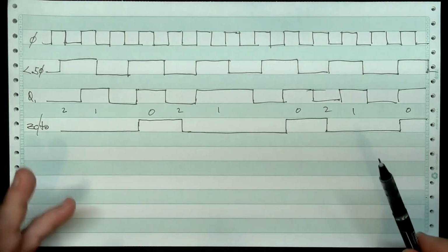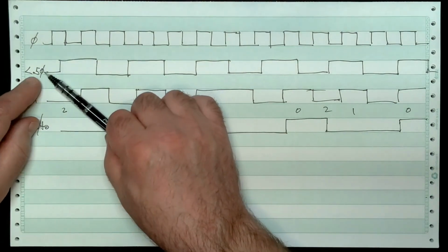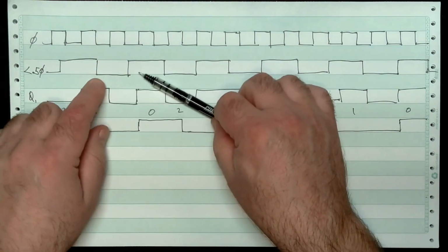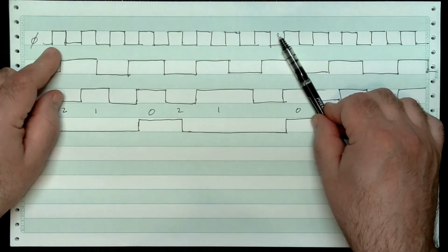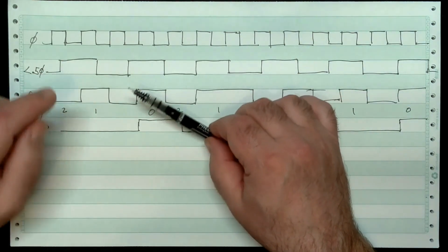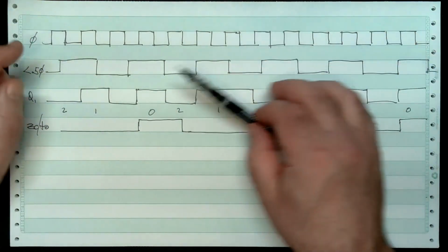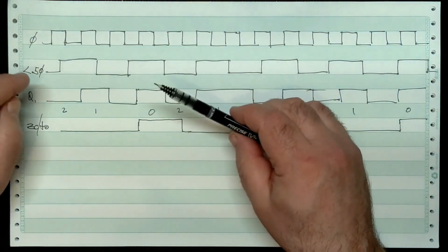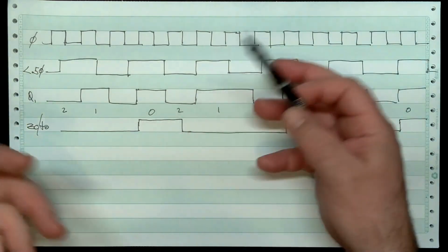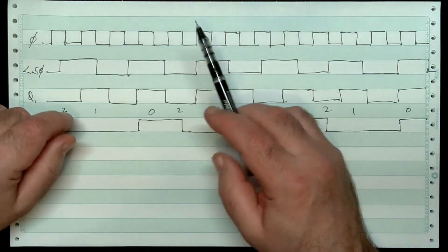Why does it jitter? It jitters because this frequency here is not perfectly phase locked to the system clock up here. As long as that's the case, which is 100% of the time, if these two come from different oscillators, they're in different what we call time domains, that don't originate in the same place. They can't be.